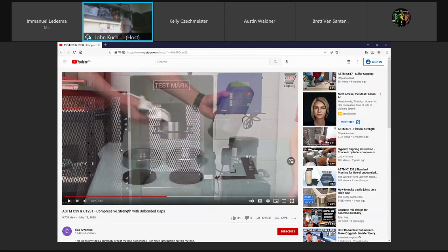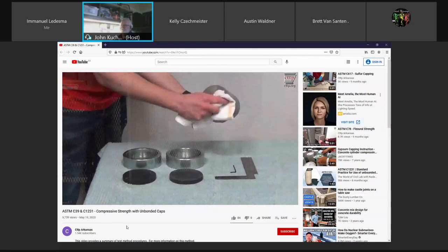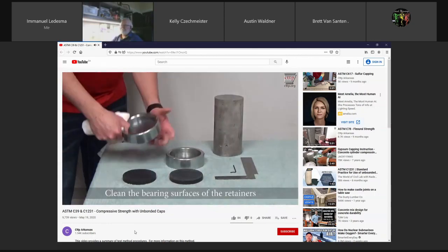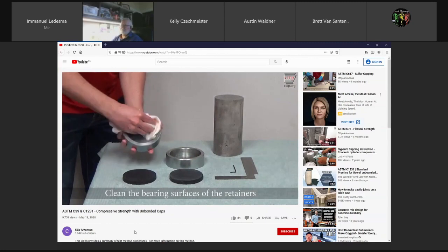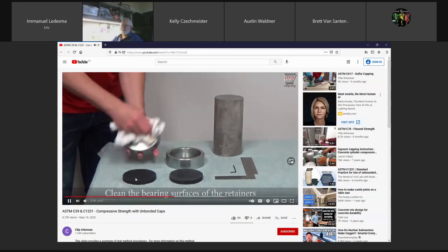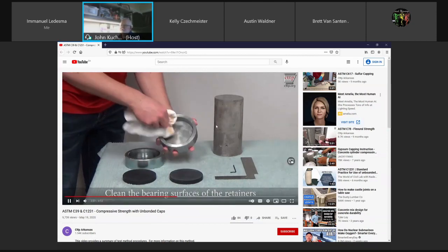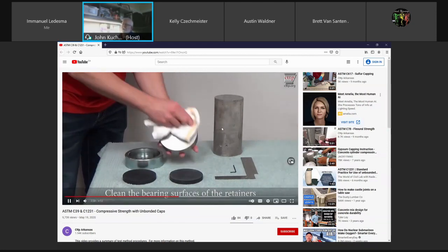Like I said, I used these when I was in the precast industry for our own benefits, but now CSA, as an independent lab, you can't use them. In the States, ASTM still allows them. There's the difference. These are neoprenes. They are a certain durometer number, and you'll use different ones if this is high strength concrete or normal strength concrete.